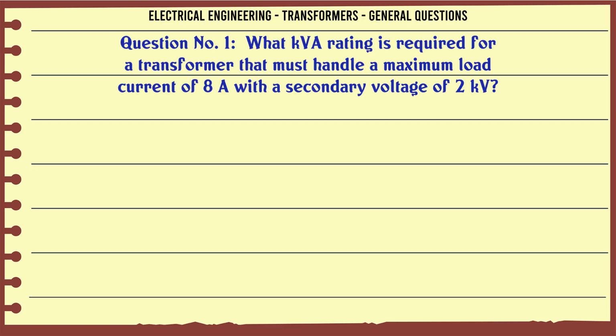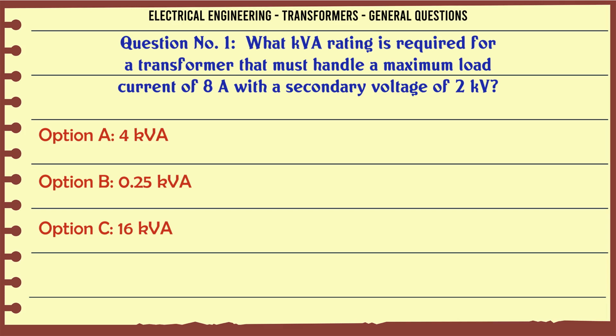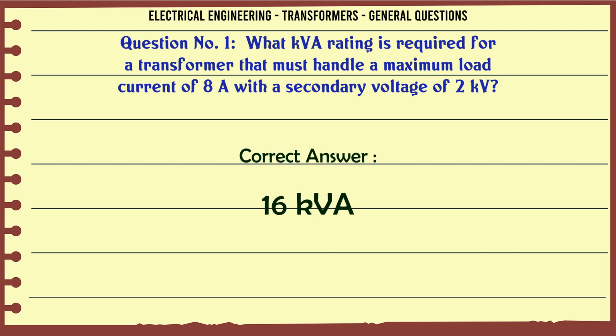What kVA rating is required for a transformer that must handle a maximum load current of 8 A with a secondary voltage of 2 kV? A. 4 kVA, B. 0.25 kVA, C. 16 kVA, D. 8 kVA. The correct answer is 16 kVA.